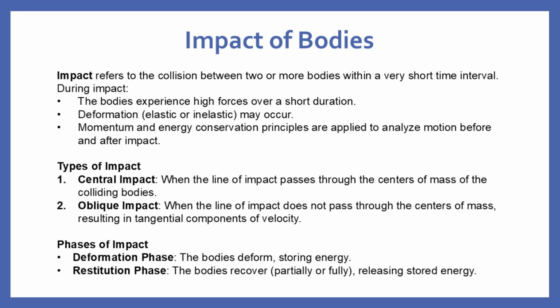Impacts are categorized into two types. Central impact occurs when the line of impact passes through the centers of mass of the colliding bodies. Oblique impact happens when the line of impact does not pass through the centers of mass, resulting in tangential velocity components. The impact process has two phases. Deformation phase: the bodies deform, storing energy. Restitution phase: the bodies recover, partially or fully, releasing stored energy.